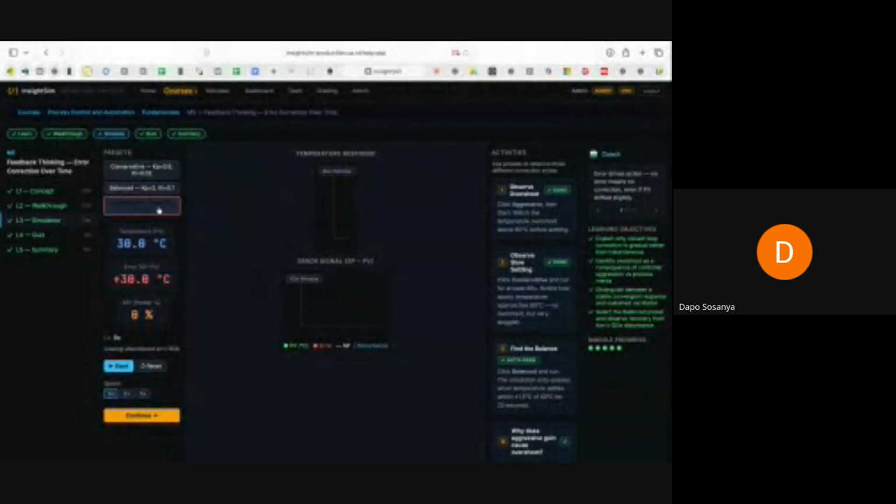When there is overshoot, we should have looked at the value of this MV at which it reaches set point. At set point is the maximum energy you need to maintain stability. Any energy you supply that causes it to overshoot is excess. So essentially, you have wasted energy. And energy is a critical cost factor in the plant.